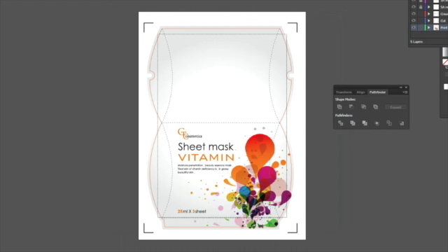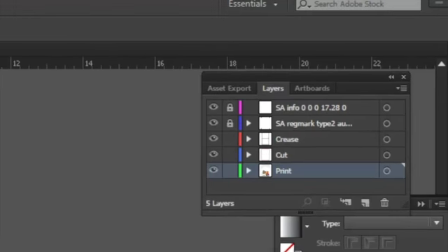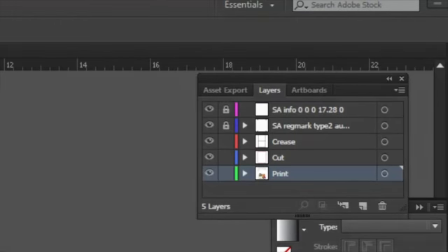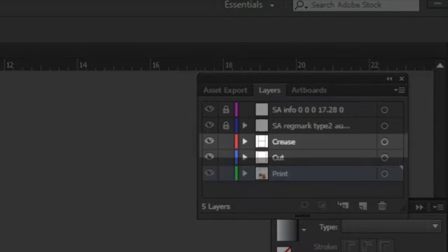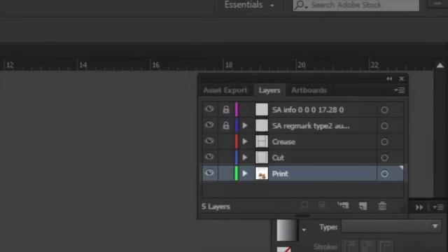In the lesson on conditions, we learned how condition presets can be assigned to each layer. To demonstrate how this can be helpful in the print and cut process, we have a package design that has both cut and crease lines, with each condition being assigned to tool holder 1 and tool holder 2 respectively, with appropriate tools mounted. If we look at the design's layers, there are 3 different layers: the crease layer, the cut layer, and the print layer.